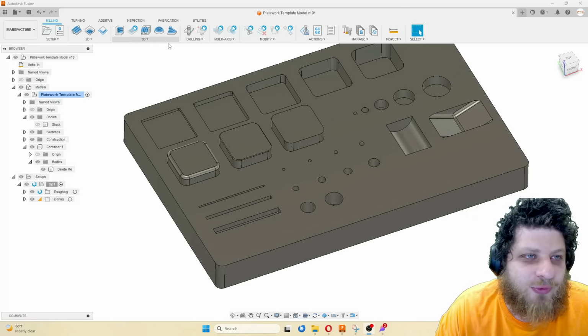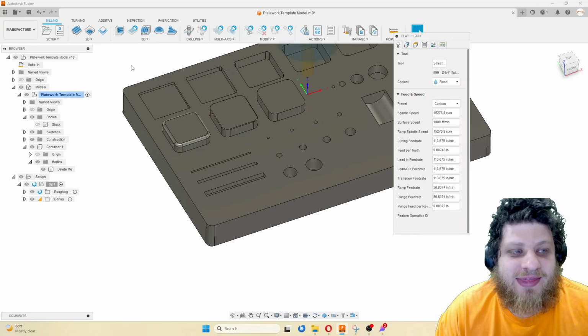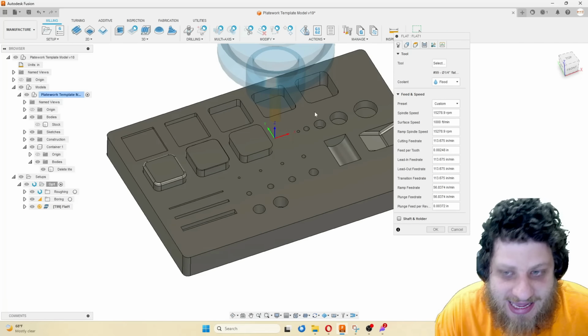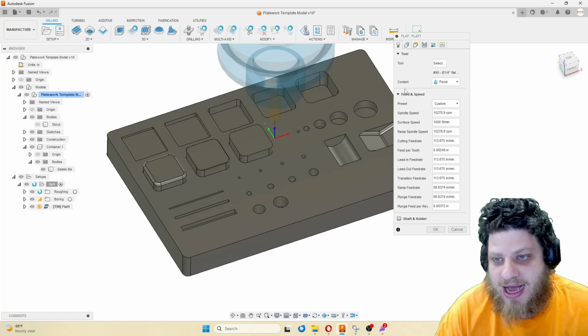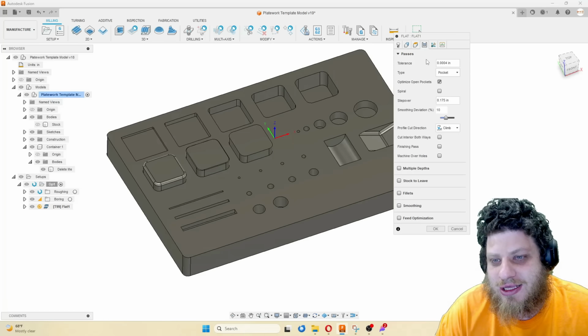The next toolpath we're about to do is honestly my favorite toolpath in all of Fusion, and that is flat. Flat can do both floor finishing and it can finish the walls of pockets. The problem with flat is you can't turn on tool diameter compensation, or wear comp.